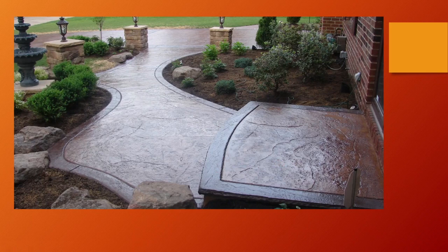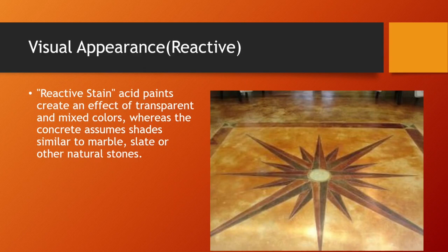Unlike tarmac, where you're going to get various bits of vegetation growing, you're going to get oxidization of the tarmac as soon as it's laid, so eventually it's going to break down through electromagnetic radiation, e.g. sunlight. It starts to break it down, starts to fade it, and starts to create what's called alligator effect, crocodiling, and starts to break up with something else called freeze thaw, which we'll come on to a little bit later in this presentation.